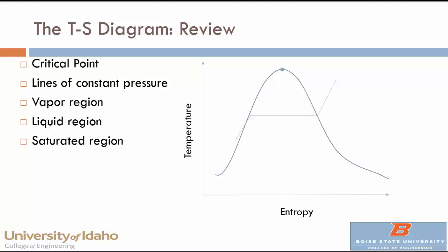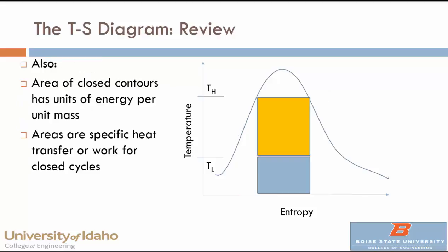Some new refrigerants, the ones in the 400 family, for example, are not pure substances. They're blends. And one of the things that happens is that line is no longer flat. It introduces a concept called glide, which can make some systems more efficient. We're not going to get into that. That's kind of a subtlety here, even though the example we're using is a refrigerant that does exhibit glide. It doesn't exhibit very much, so we're not going to worry about that for the purposes of this course, but you should be aware of that.